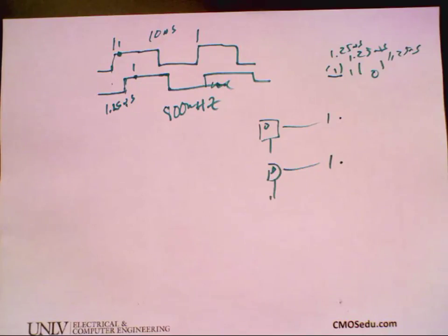Okay, what I'm doing, each path is outputting data at 100 megahertz. I'm saving it at a slower rate. I'm saving a word, say 4 bits at a time. That means I'm saving it after I get 4 bits in. I save those 4 bits, so it gives me more time for the digital data to set up before I clock it and save it. Then I read that out with MATLAB, so I read a word out in parallel.